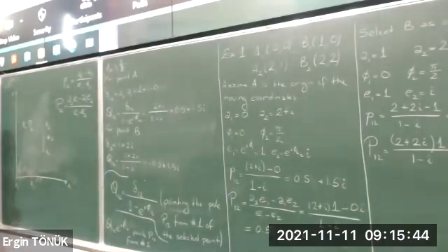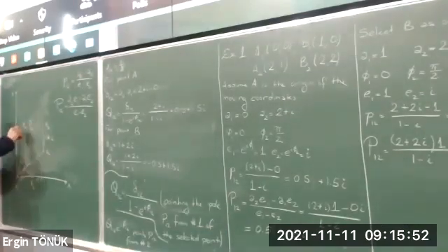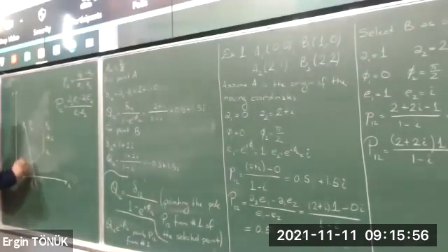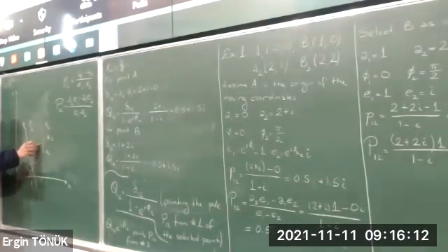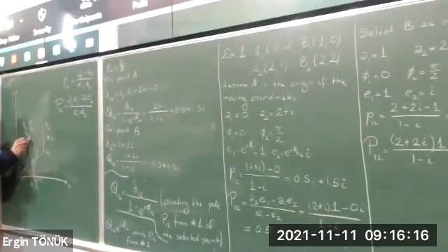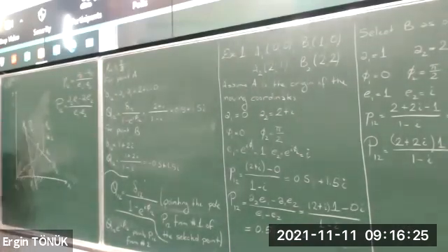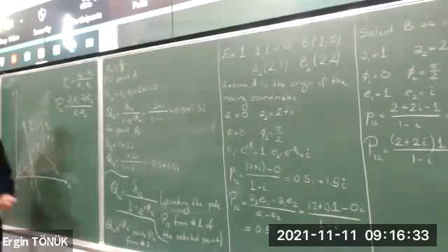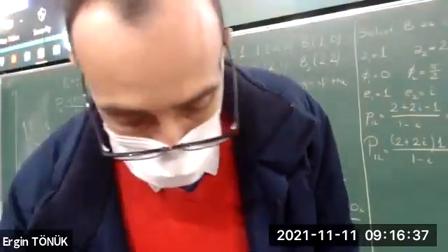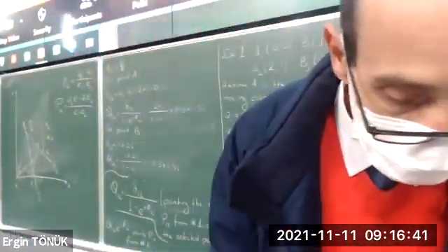So I'll just draw the perpendicular bisector of A1, A2. So I'll just sketch a line. Then I'll draw a perpendicular at the midpoint. But in most of the CAD packages, you just select the 2 points after you say draw perpendicular bisector. That's all. Okay. This line is just for me to guide it. And then this one. And this one. So if you like, this is what we call B12, the perpendicular bisector of the homologous points B. And this is A12, and we find the very same pole. Okay. Any questions on this?